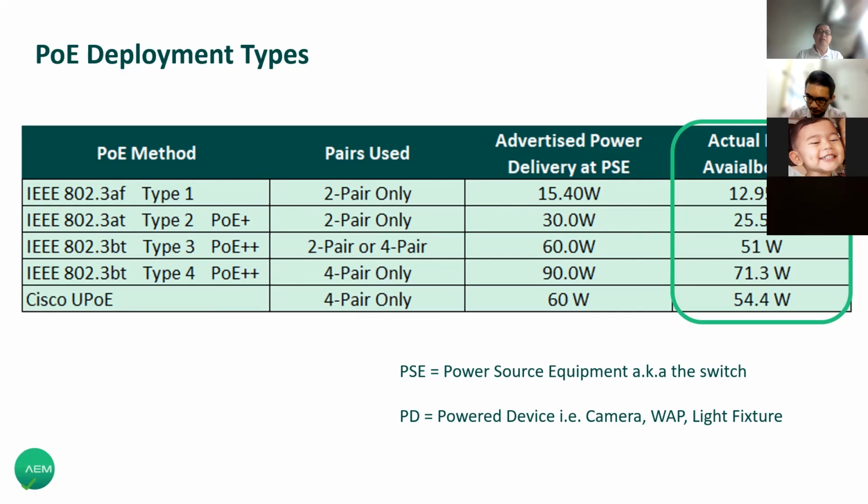If you want to pass the standards, this is the standard that stipulates pass or fail. So if your measured value when you do the PoE test, the real or actual power, is less than the table here, you will get a failure. In other words, you fail the IEEE standard. You should not be less.